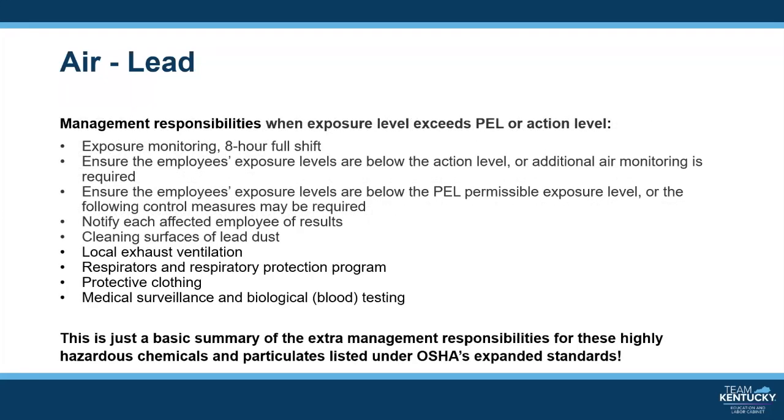And with lead, again, we're seeing that management has extra responsibilities when the exposure exceeds the PEL or the action level. This could require exposure monitoring for an 8-hour full shift workday. This would require that management ensure that the employee's exposure level is below the action level or additional air monitoring is required.